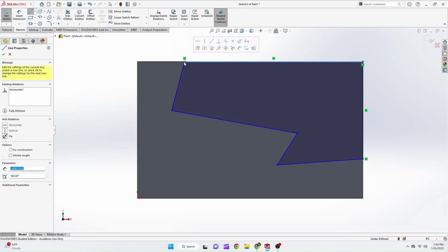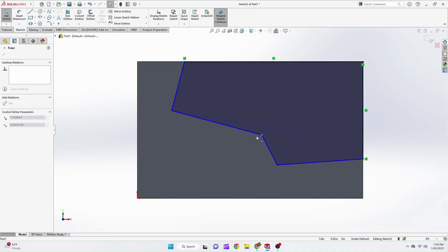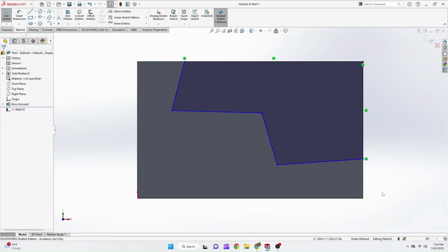So usually when you start sketching, there might be 1 or 2 black lines. In my scenario, there's 2 because I referenced this to the top and the right edge. But there are still several blue lines. If you look at that just like this, you can see obviously very blue and very movable. That is not what we want.